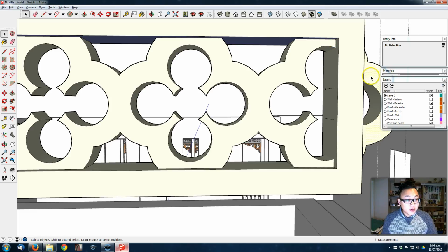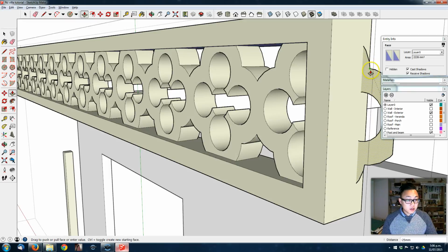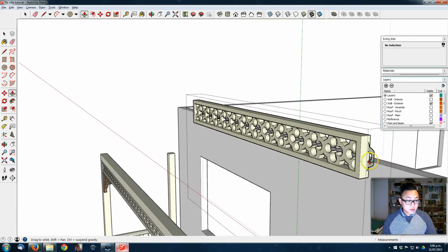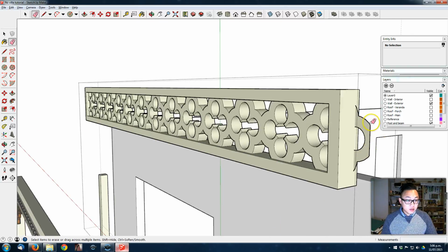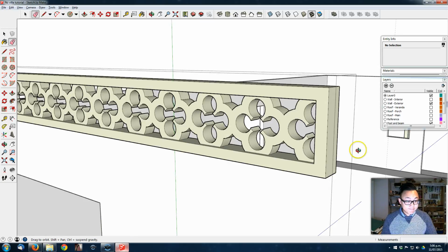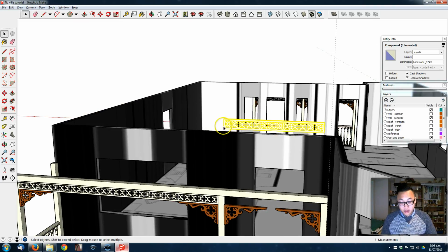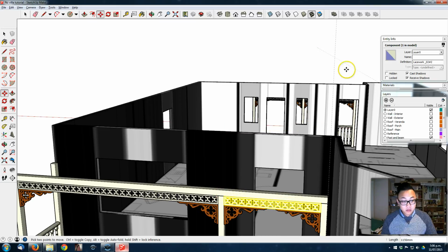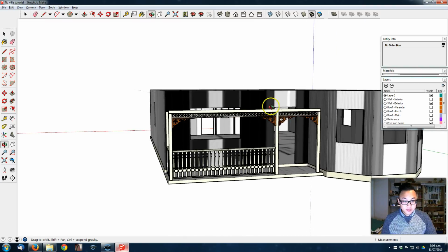And select that face, extrude it back so it disappears. Sometimes it doesn't disappear, so you can just erase its line and the face will disappear. So now it's all cleaned up, we can just pull it back now. Delete. Okay, so now we've got our details.